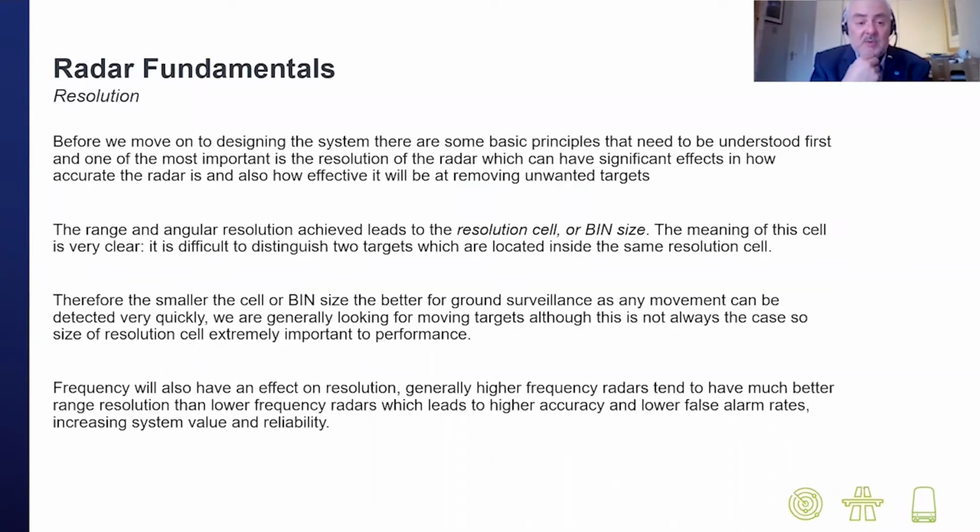Frequency also has an effect on resolution. As a general rule of thumb, high frequency radars tend to have much better range resolution than low frequency radars, which gives higher accuracy and lower false alarm rates.